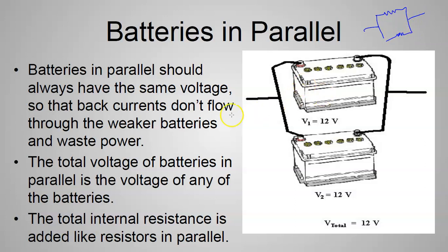And this is the same kind of thing. Here, coming from the circuit right here, this would put in 12 volts. This would also put in 12 volts, but we have to add these differently. They don't add like they do in series. They're kind of like the resistors. We don't just get 24 there. What we actually get here is 12 volts. Now, it's really important that the batteries have the same voltage. Okay, they need to match.